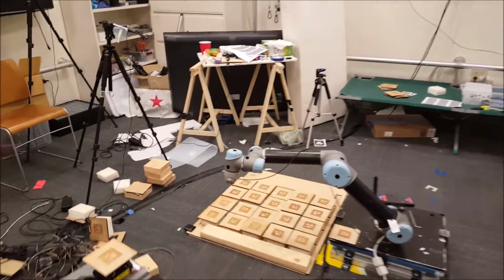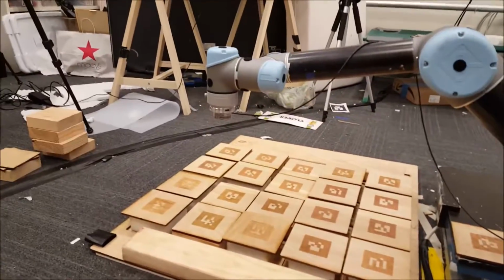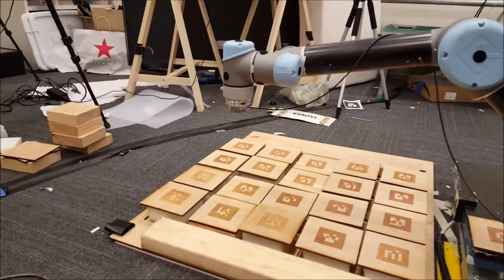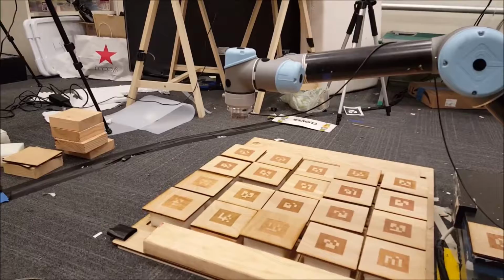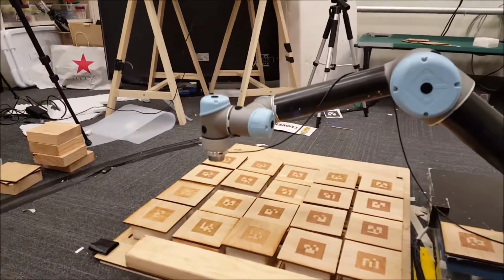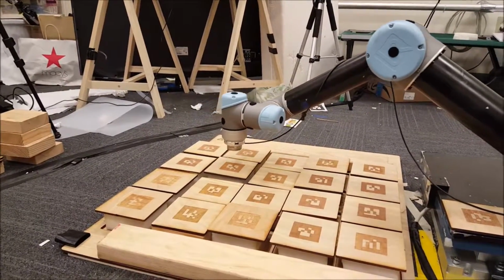So now we're going to move the UR5 into a more favorable position to get it ready to start testing. As you can see, the favorable position has put us in a way such that the end effector is oriented where the force sensor is ready to compress the blocks in Z and read forces. So now we're going to go down to a specified height above the block and begin traversing the grid.